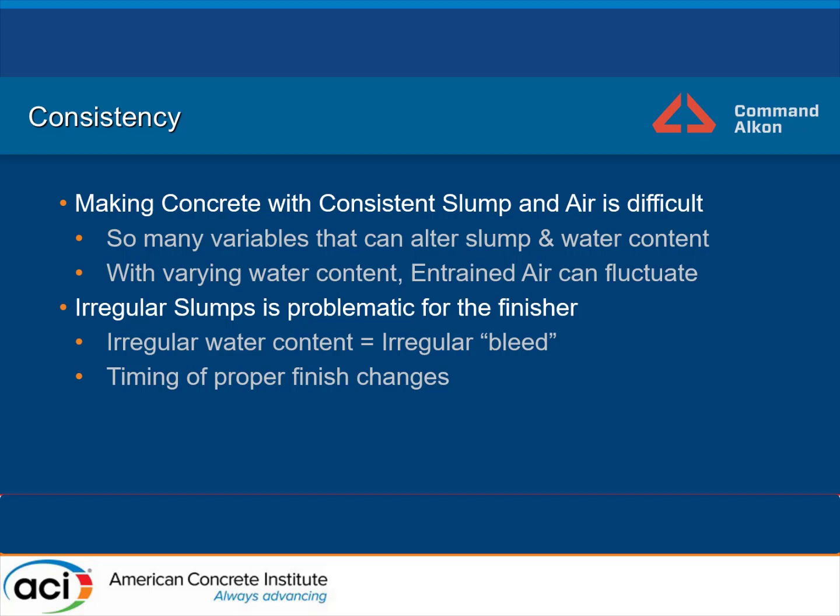I always say the best finishers in the world are more artists than they are truly laborers. And people just don't understand that. They're dealing with different mix designs, cement contents, ternary blends, and they have to be able to figure out during the day, with the varying weather conditions, how the timing of that finish needs to take place.